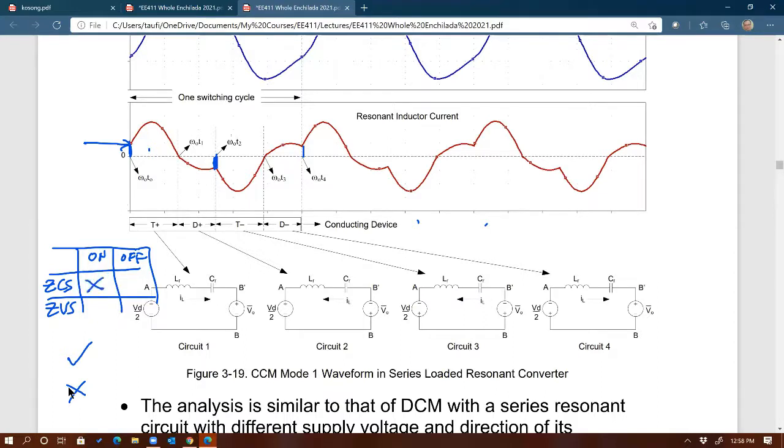How about at turn off? Yes. Why? Because there's no current after. How about before? Because it's sinusoidal before, and zero after. Good, you got it. It follows a sine wave right there. So if you zoom in from the left, before you turn off the switch, because it's following a sine wave, it gradually goes to zero. So therefore T0 minus will be zero. T0 plus has to be zero because it's off already after T0. So therefore, it is a yes for zero current switching.